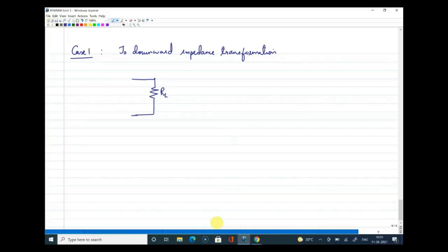So what I will do now is I'll introduce a matching network, or I'll introduce an element here, and that element is a parallel capacitor, and I'm calling the capacitor value C1. Right. As we discussed in our previous class, we know that parallel RC can be converted into series RC, and in that case, definitely the resistance is going to have a smaller value than the original resistance value of RL. Right. So that is possible by addition of this capacitor.